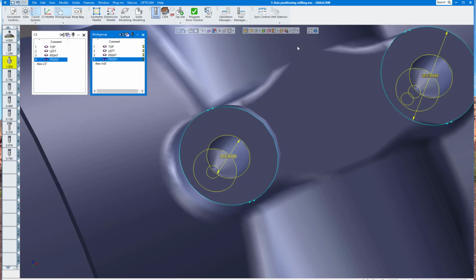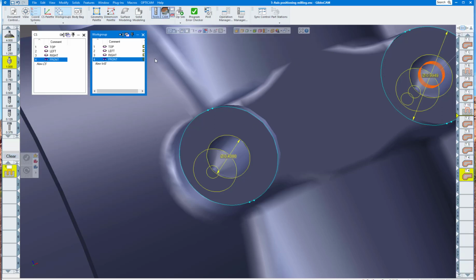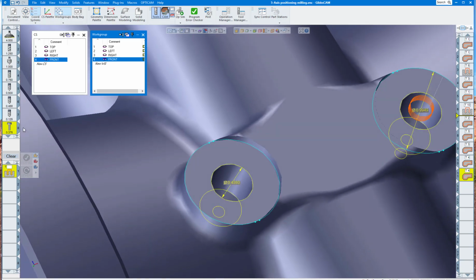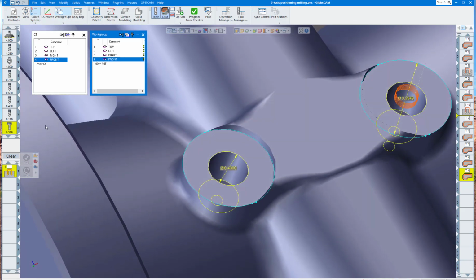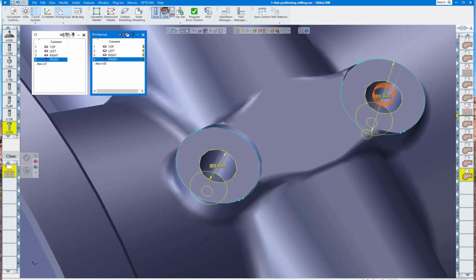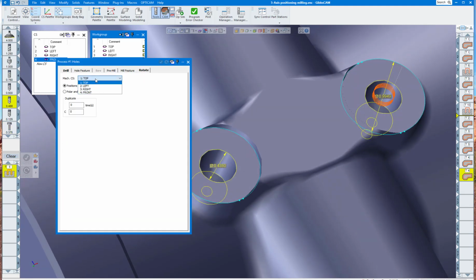So we're about 4 3/8, 7/16. This is going to be this 3/8 NPT tap. So the first thing I want to do is, of course, drill it. It's actually a little bit bigger than 4 3/8 for the tap. We're just going to use this drill here. And again, make sure you're on the front.